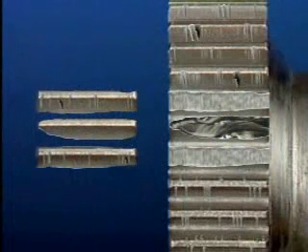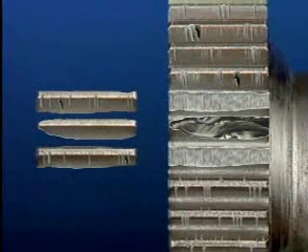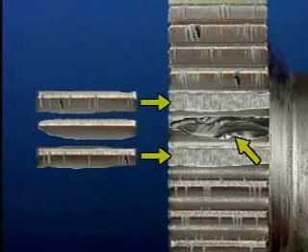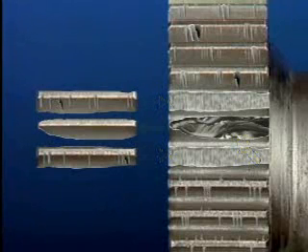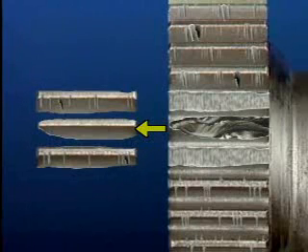A close inspection of the broken gear in this case shows fatigue failure with a well-defined eye and adjoining teeth broken by overload with a rough appearance. A look at the crown or top portion of the tooth that broke due to fatigue failure indicates that the tooth was not deformed before it failed. This is also evidence that an external overload was probably not a factor.